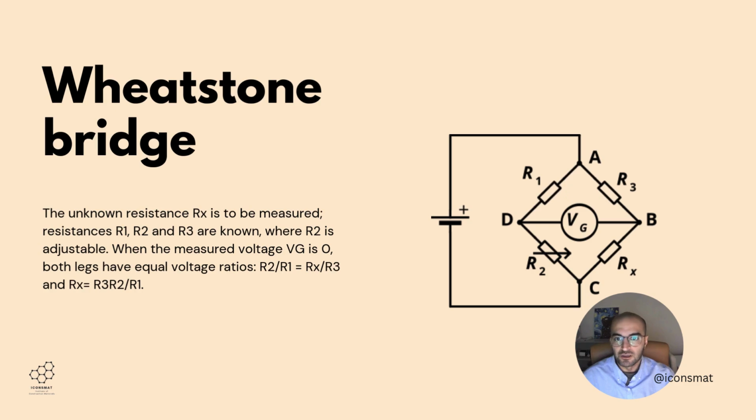When the load value increases, the resistance will change as well, and we are forming a linear relation between every reading. So next time when the strain gauge gets loaded by another load, we can predict the resistance and format our formula.